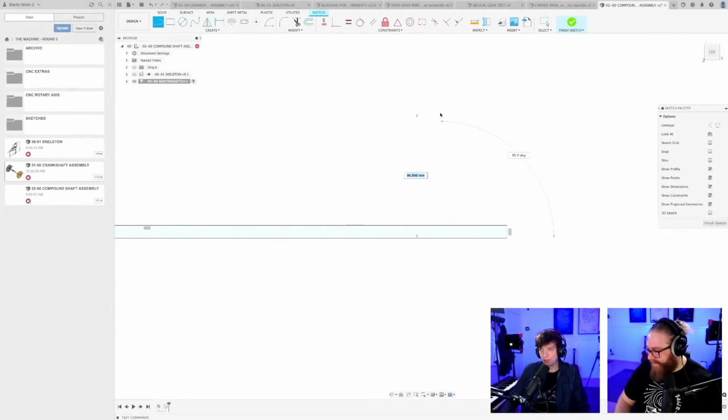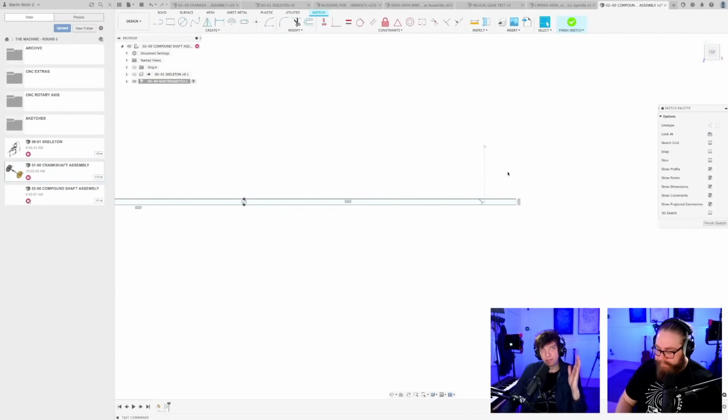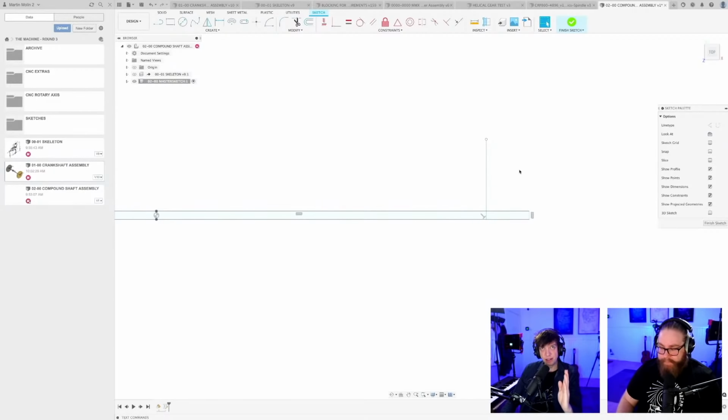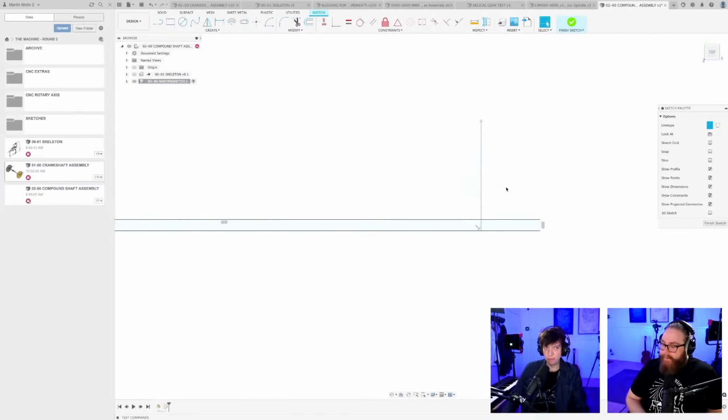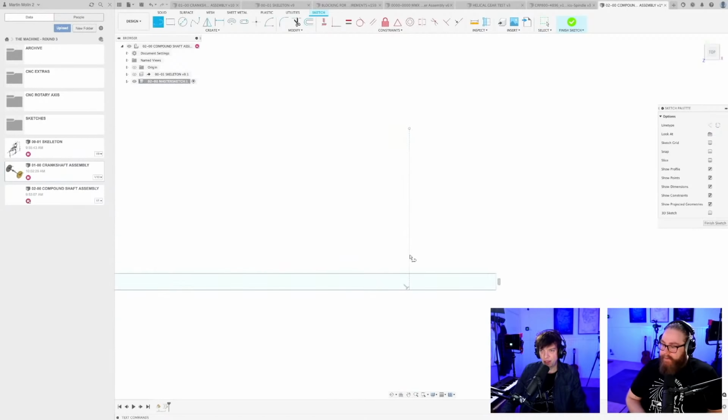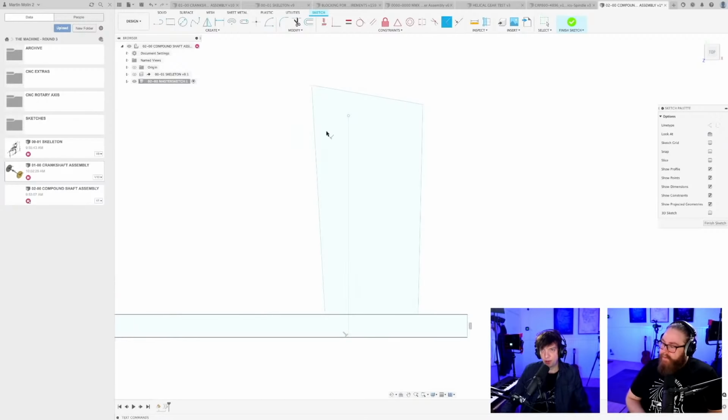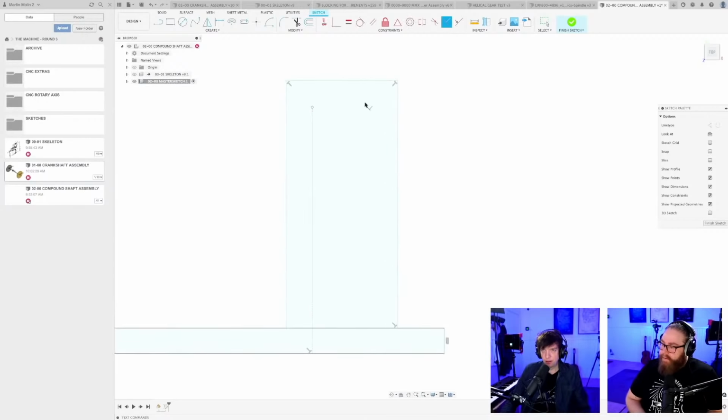So here I'm going to start to CAD. And another design principle: all my measurements go to the center of stuff. So it doesn't matter if this gear is 36 millimeters wide, I don't start on the left side of the gear. I always measure to the middle this time around. So I start with a middle line, and then I make the shape of the gear here. Often when I've been CADing so far, I measure stuff to the edges of them, which is suboptimal. So just constrain it straight, and I'm just gonna drag this until it snaps into the triangle.